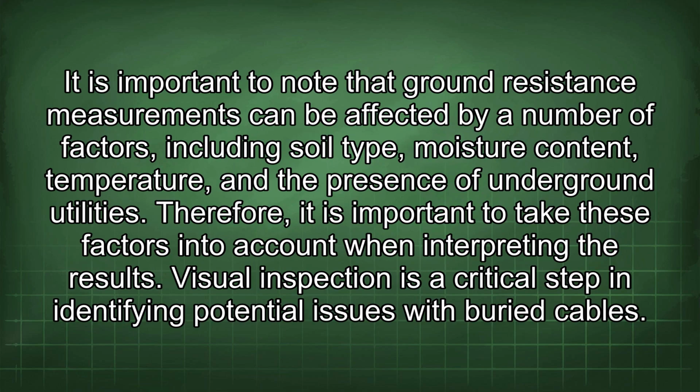It is important to note that ground resistance measurements can be affected by a number of factors, including soil type, moisture content, temperature, and the presence of underground utilities. Therefore, it is important to take these factors into account when interpreting the results.